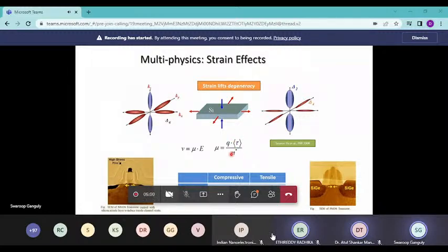As it turns out, when you apply strain like this to the PMOS device, then the scattering time goes up, because that strain changes the band structure of silicon from looking nicely symmetric in all three directions. It becomes like this. And then electrons are no longer able to scatter as easily between all these 6 valleys.